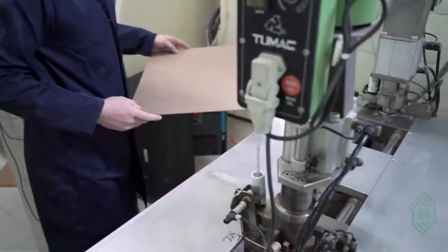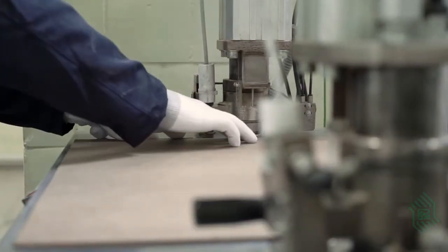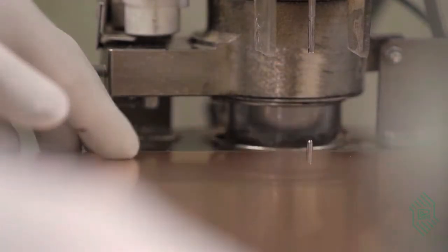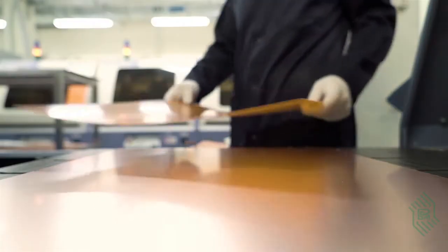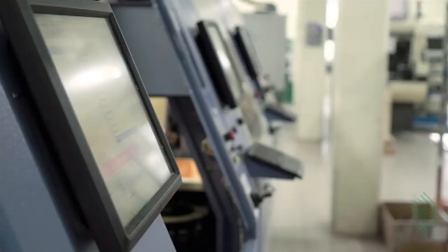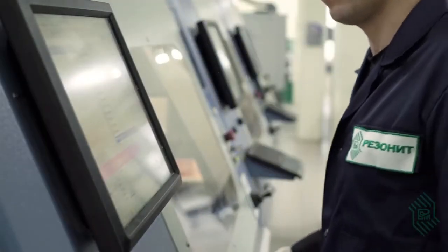For drilling the holes, the PCB panel is assembled into a stack. It consists of a lining material to eliminate burrs on the reverse side of the fiberglass, and the cover plates are made of aluminum to minimize the drift of the tool during the drilling process.